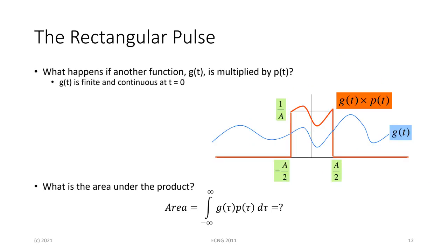Now the thing about the pulse is, again, if you take our signal and you multiply it by a pulse, what happens? Because the pulse works like 2 unit steps, everywhere the pulse is 0, it will get rid of the signal, and everywhere the pulse is 1, it would keep the value of the signal.